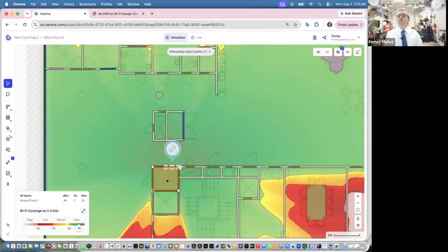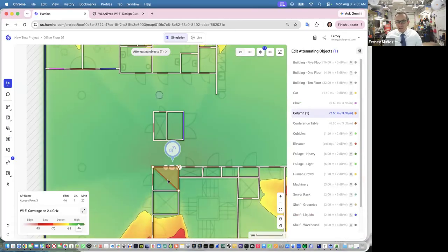Well, if you go and measure, then you can just draw an attenuation object, because if you measure on one side, let's say it's negative 40, and then you go to the other side, and it's negative 75, then you say, well, this entire box, whatever size it is, loses 35 dB, then you can just draw it that way. Because if you do 30 and 30, that's going to be 60 dB. And then some free space path loss along the way.